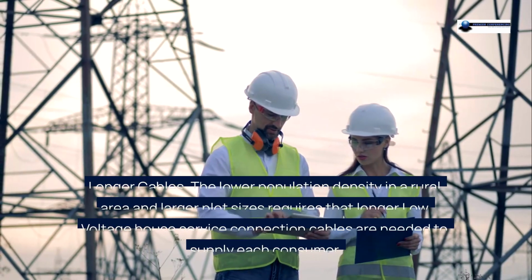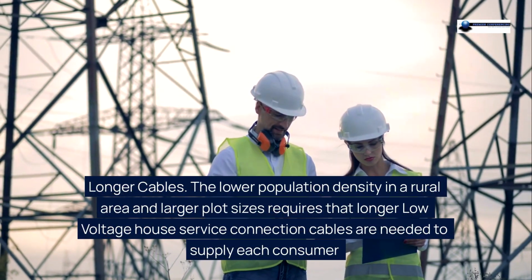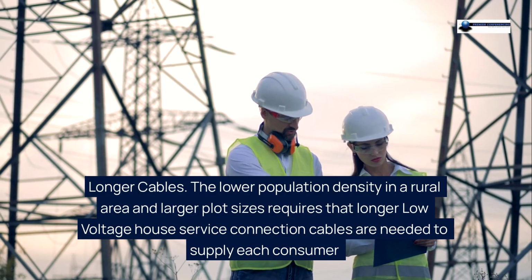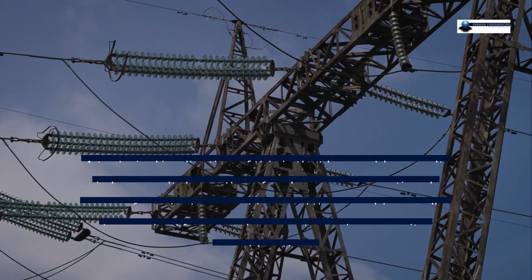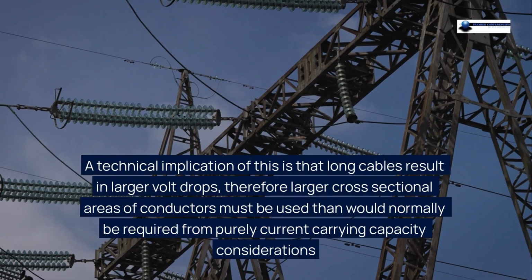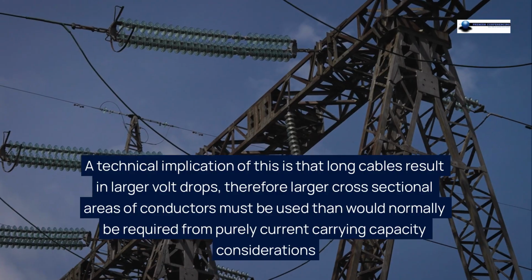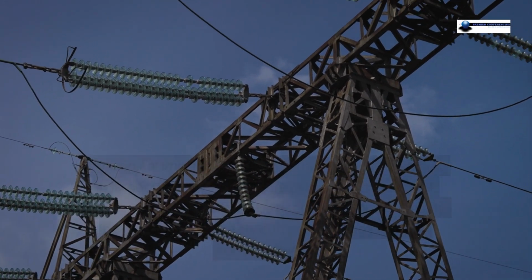Longer cables. The lower population density in a rural area and larger plot sizes require that longer low-voltage house service connection cables are needed to supply each consumer. A technical implication of this is that long cables result in larger volt drops. Therefore, larger cross-sectional areas of conductors must be used than would normally be required from purely current-carrying capacity considerations.